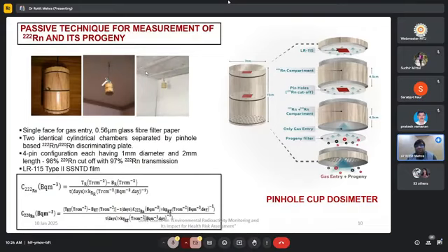So that is why they have been hung a little bit away from the wall and from the ceiling, so that only the air surrounding the detector can affect this detector, not the building materials. It has 2 compartments, where one detector is placed in the lower bottom of the first compartment, and then the second compartment. And once the gas enters from the lower side, there is a mesh which is available. So it is shaped like this.